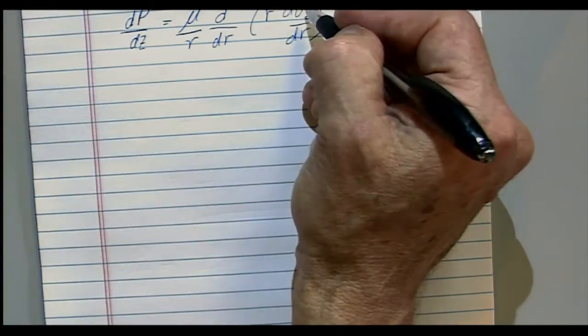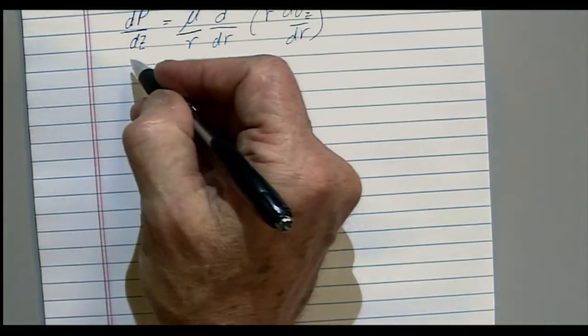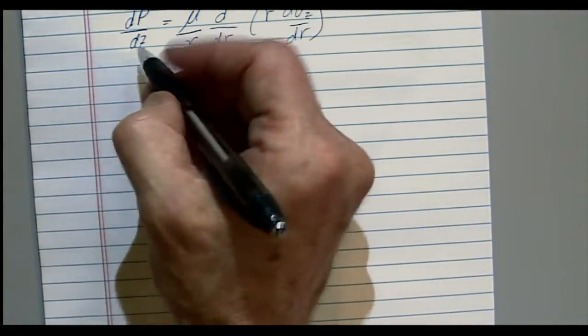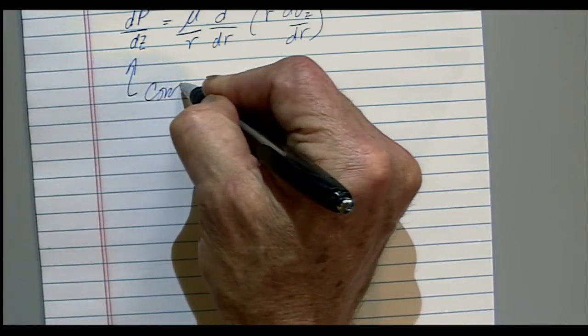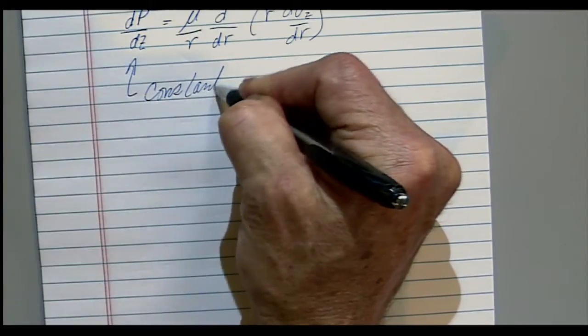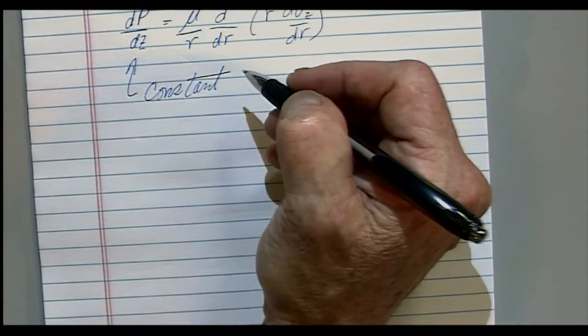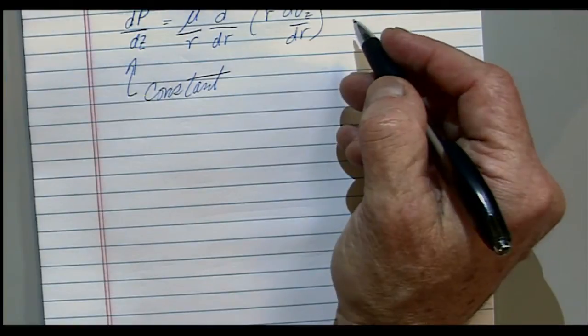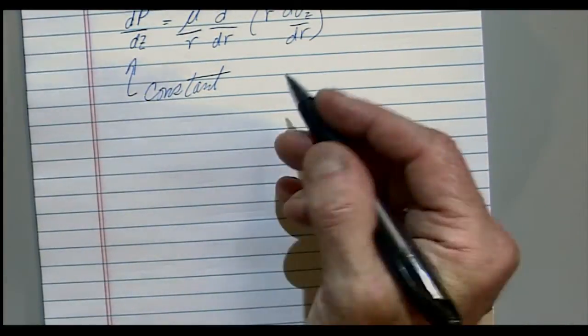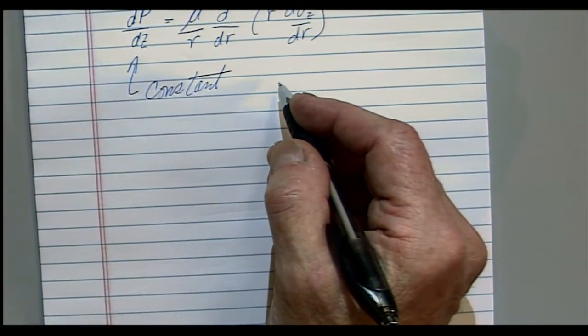So again, it's the velocity in the z direction, and the pressure gradient is a pressure gradient in the z direction. And this pressure gradient, I'll remind you, we always treat as being constant. So it's for a constant, steady flow, no acceleration in the fluid. It's flowing at a steady rate. What arrives at one point arrives at the next point later on. So this is Stokes' equation set up in particular now for cylindrical coordinates.